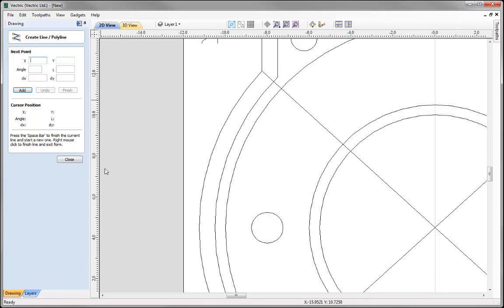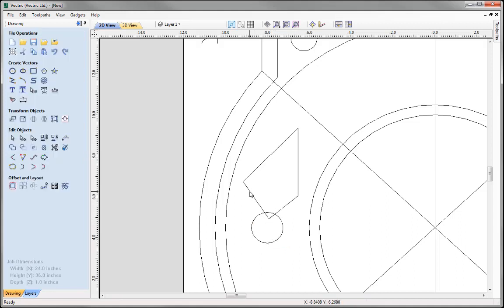I'm just going to go into the polyline tool, and then we're going to roughly sketch in the shape of my leaf. Okay, so I'm just going to come out here, come up over there, then we're going to come over here, and then join those back up. Right click here to come out of the polyline tool, select that vector. I'm going to go into node edit mode. I'm just going to box select those bottom nodes there, press S on the keyboard to smooth them, and then we could look to really transforming the shape of the vector that we've got.